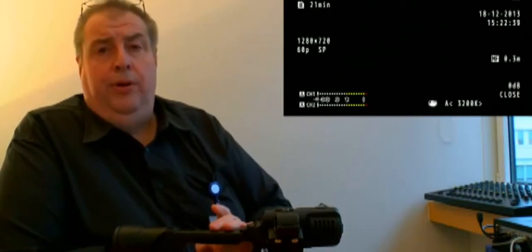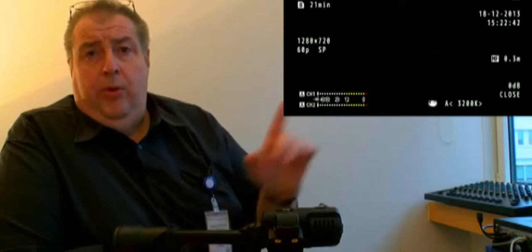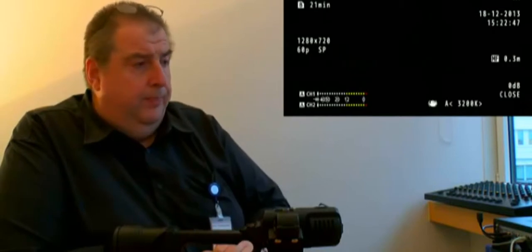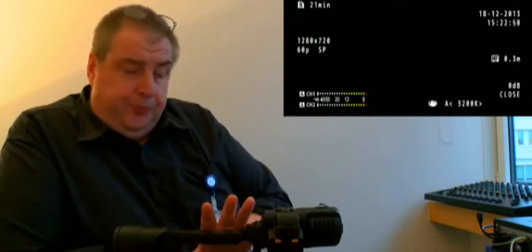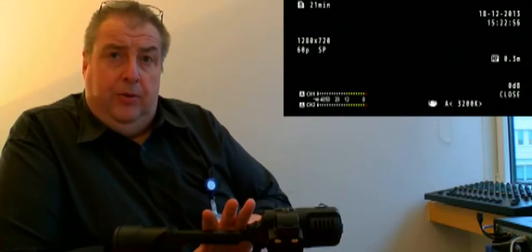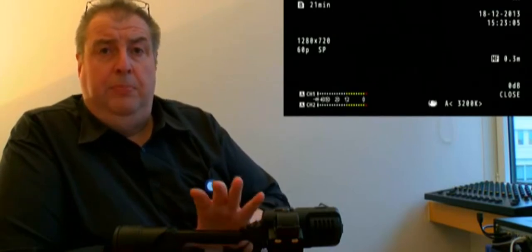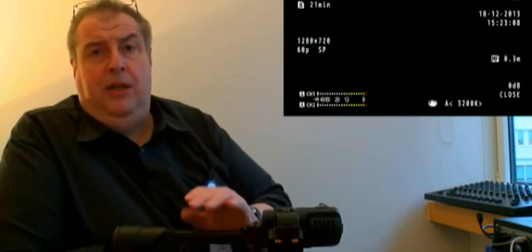Another good point is that this camera has the latest firmware, by the way. Today a new firmware is coming up, 2.08. The regular one yesterday was 2.06. We have some fixes in 2.08. Anyhow, it is important that the camera has a lot of capability for streaming. So today you can start from 300 kilobit in regular production. 300 kilobit is the base for BGAN signals. You know that BGAN needs even to come down to less than 250 kilobit. That will be one of the next generation of updates coming very soon.